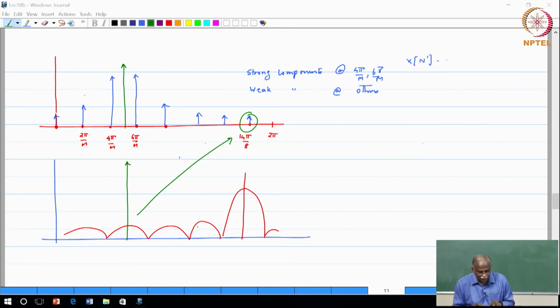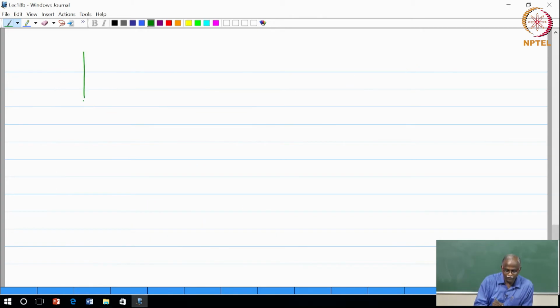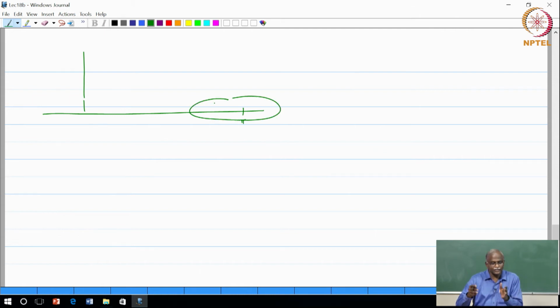If you go back, this is the frequency response. If I were to plot the frequency response of an impulse response or any signal, this is pi. If I see a lot of energy around the high frequencies, which basically means that my frequency response has components all the way from DC to the highest frequency, that indicates that there have been some sharp transitions. Usually sharp transitions are the ones that cause that.